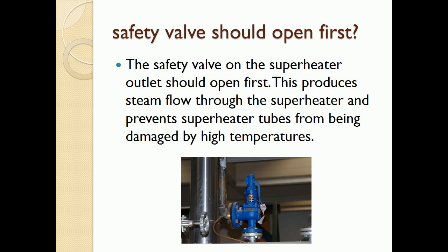Which safety valve should open first? The safety valve on the superheater outlet should open first. This produces steam flow through the superheater and prevents superheater tubes from being damaged by high temperatures.